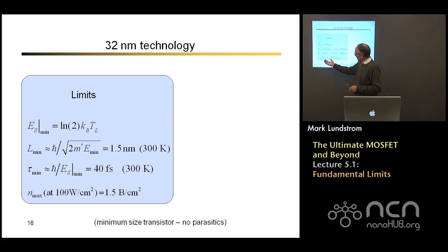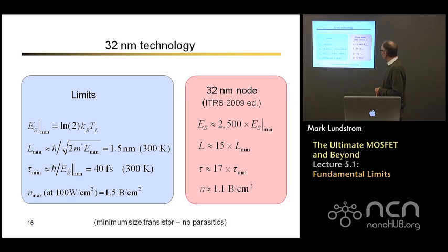So if I do standard things, I can cool about 100 watts per square centimeter. If I go to esoteric, expensive cooling, using liquid channels flowing through the chip, we can maybe get close to 1,000. But if I use 100 for more typical products, that would translate to 1.5 billion transistors per centimeter.